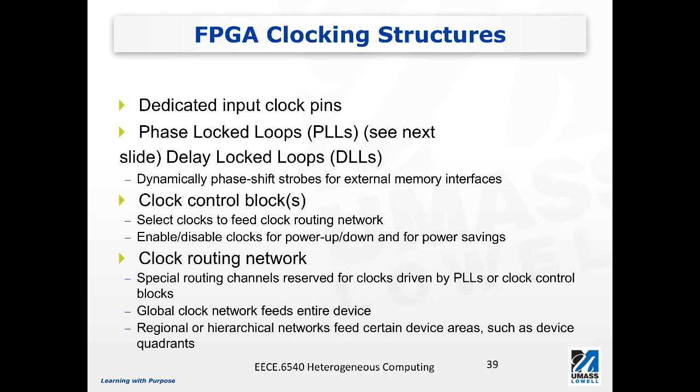FPGA clocking structure. FPGAs rely on a dedicated input clock. Internally, you can use the input clock to generate other clock frequencies using PLLs or DLLs.